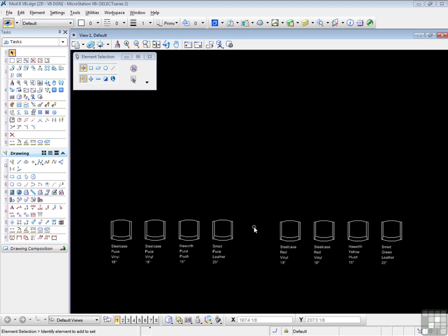MicroStation provides a facility for generating reports on tag values. The report that is generated is quite basic in content, but it can be opened by any word processor, and it can be imported into spreadsheets and database managers. Generating a report is actually a two-part process.